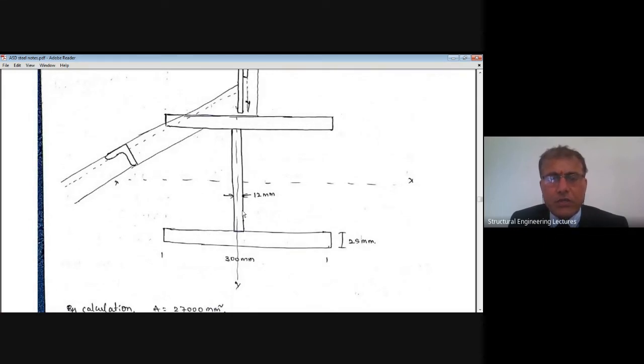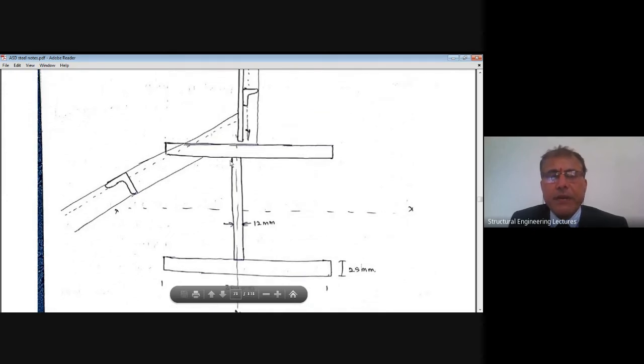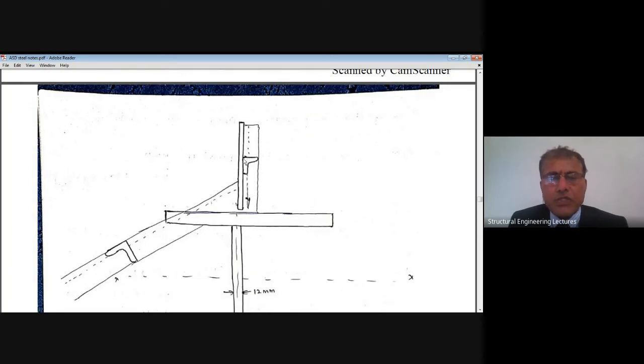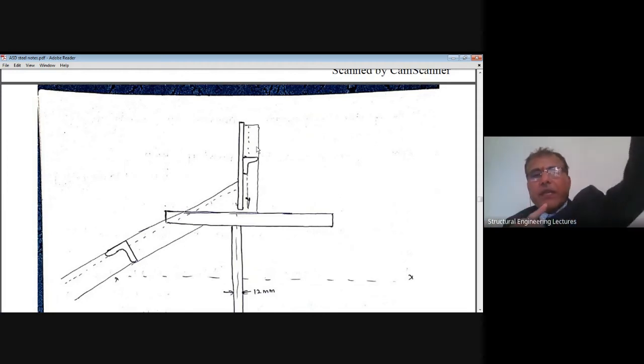This is a 1012 mm and 325 mm. This is a welded plate girder, welded by fillet welds. That also we will design at the end. That is how the cylindrical portion, the vertical plate, is stiffened by horizontal stiffeners, right? Like this, horizontal stiffeners at every 1.5, 1.5, 1.5, and they are also provided with stiffeners running in the vertical direction. These are also the same angles, ISA 65 by 65 by 6, running along the periphery